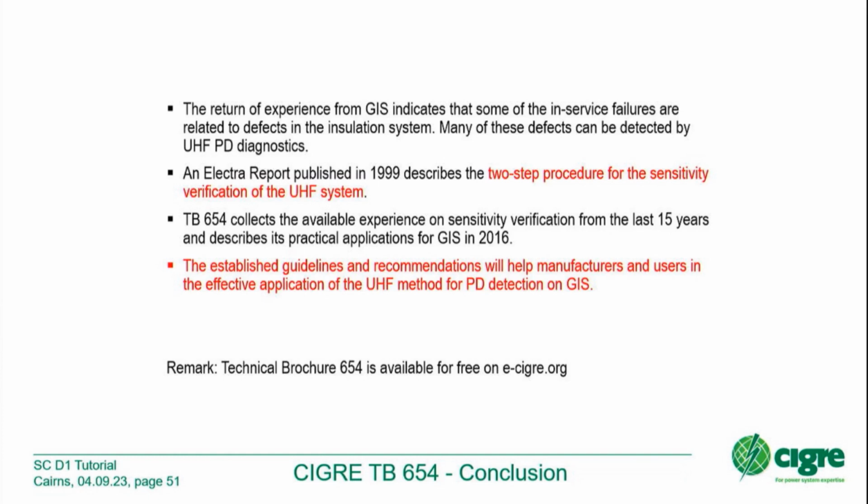Because if you have this topic which you mentioned, I think this is not the standard case. This is an exception for this topic, let's say. And the lucky point is if the same manufacturer is extending the old GIS, that is all in one hand. And of course, they have to follow the actual standards. But this is always a problem. If you have old equipment, maybe with some PD, and you are coming up with a new one, and the new system is detecting PD from the old one, who is responsible for that?